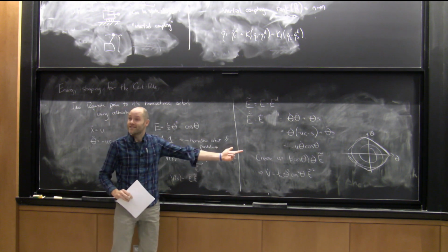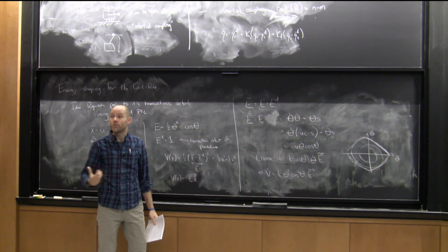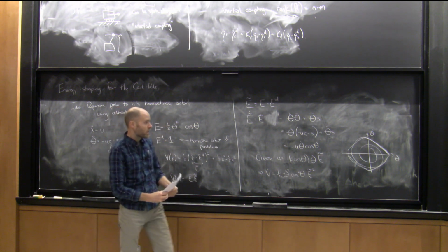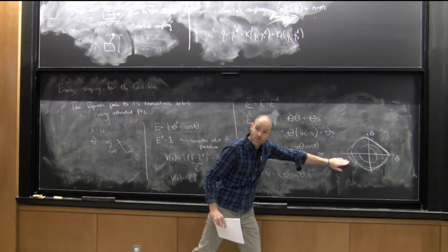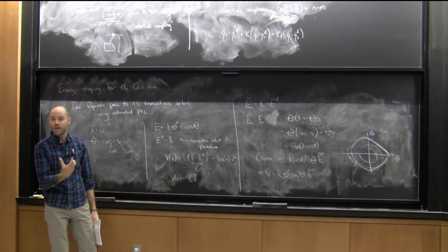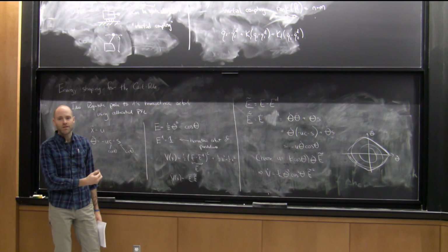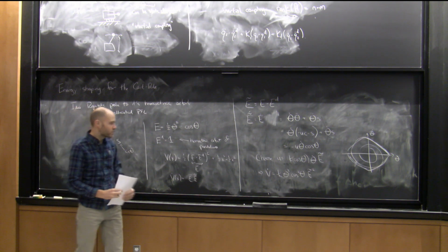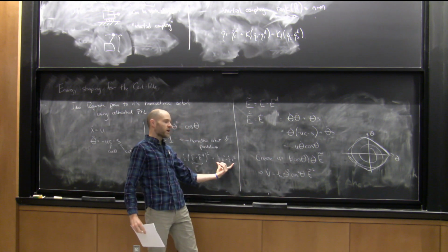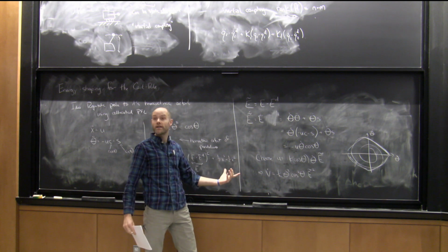Throw a few more terms in here, show that it still goes downhill, and you'll simultaneously pump the energy up in the pole, but also keep the cart near the middle, and eventually stabilize at the bottom. Okay? And this one is actually really easy to type in. You have a few parameters that you end up tuning. This K, there are feedback gains on the cart too, but it's very easy to find parameters which stabilize the system in practice. Okay?